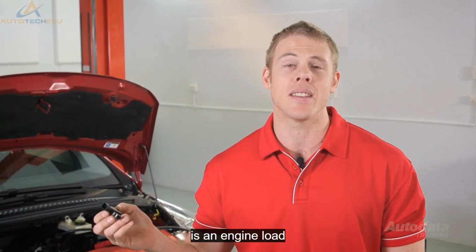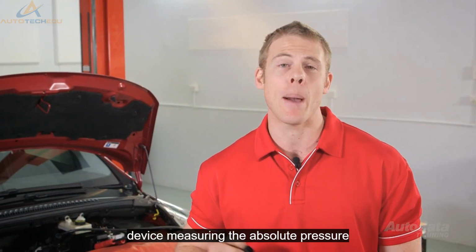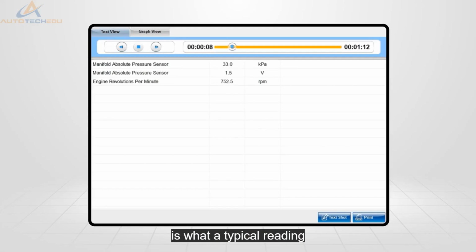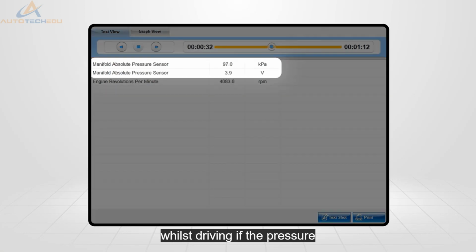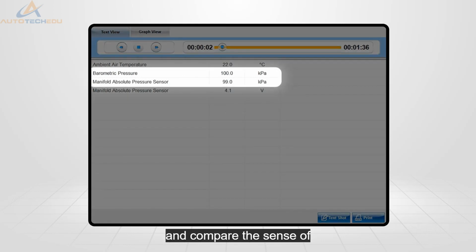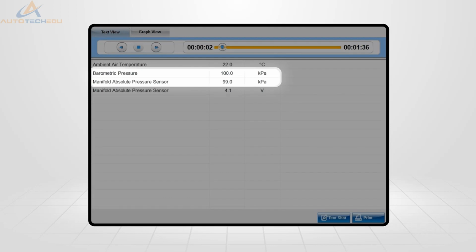The MAP sensor is an engine load device, measuring the absolute pressure within the manifold. Here is what a typical reading should look like on a smaller capacity engine from idle to around 3000 RPM whilst driving. If the pressure is low, so is the voltage. As the pressure increases, so too will the voltage. A quick integrity test for a MAP sensor is with the engine off, compare the sensor value to atmospheric pressure. They should be the same.